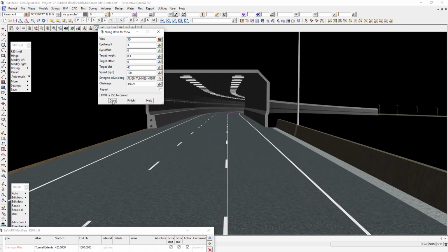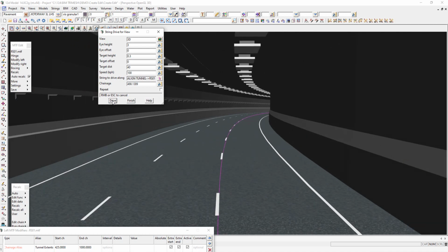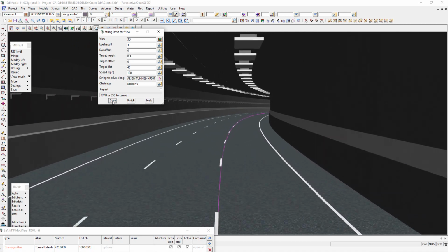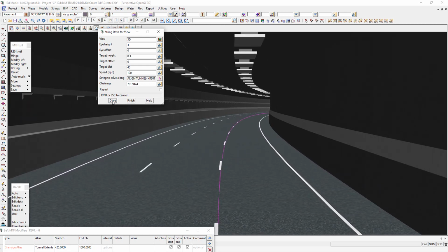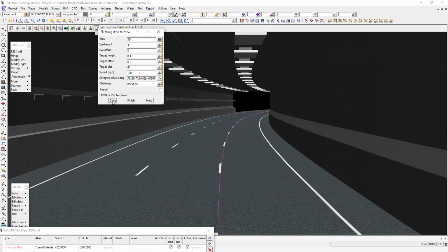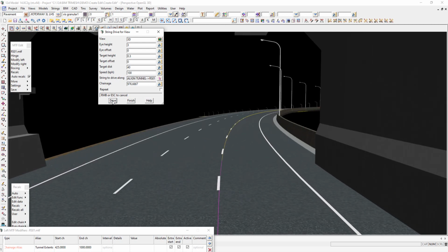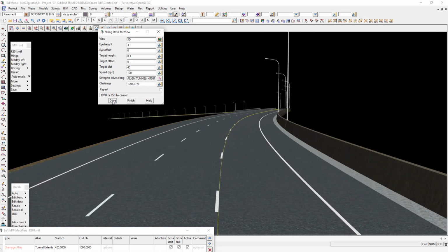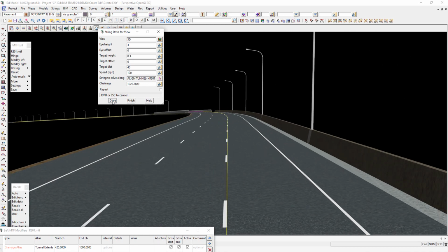You can obviously get areas and volumes information from the trimeshes with that interface string on the edge that I showed you. You can attach interface, decisional templates for your final batter. You can create a tin from the bottom of the trimesh that was on that profile definition that I drew, and once you've got that tin from there, you can obviously then create a super tin and get volumes and information about your future design.